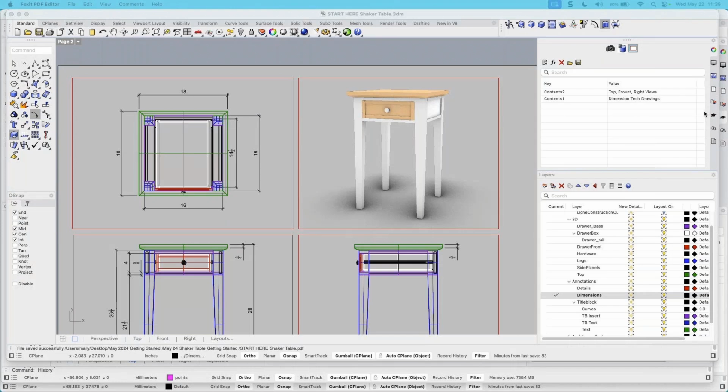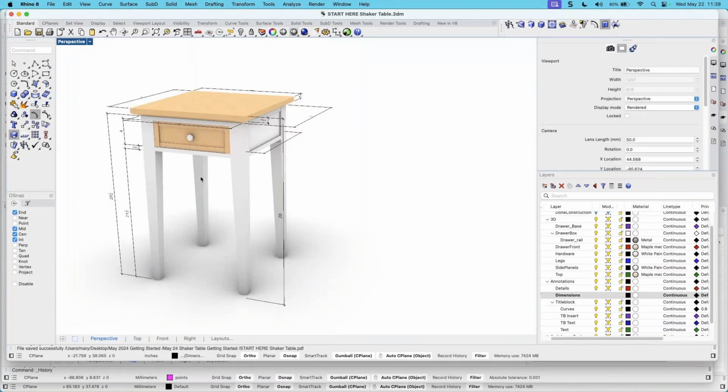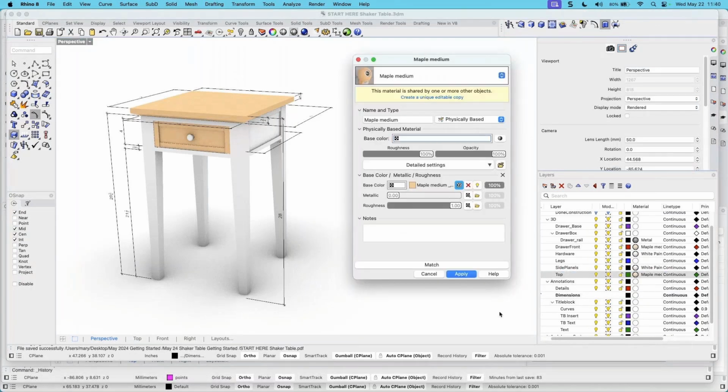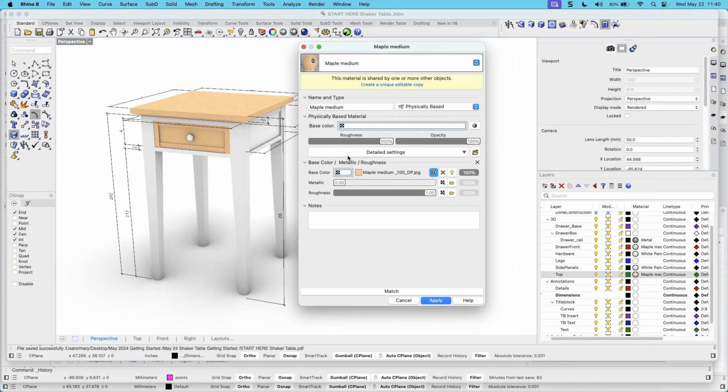So we just got to find out now what property, materials property, that's just editing the material, right? So when you find a material to edit, there are a couple ways to do it. One way is right here. You can pick here and bring up, these are the material properties. That's how you change the properties of your material. Okay, so you can get to it from here, right from the layer if it's assigned by layer.